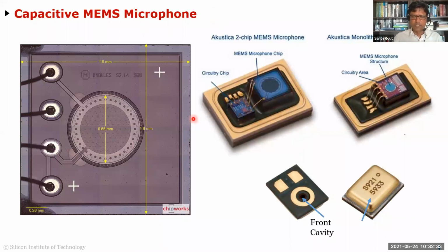So this is like a typical microphone. This is one of the popular microphones by a company called Knowles. And you can see this is actually what's called a micro electromechanical device. It's actually a chip, but it's actually got a mechanical device. Just a suspended diaphragm over here. So there is vacuum underneath this. So when you speak, this will move this diaphragm, and the capacitance will change between these two electrodes. And then you have an IC which detects that change and converts it into your voice. Okay. So this is a typical microphone.